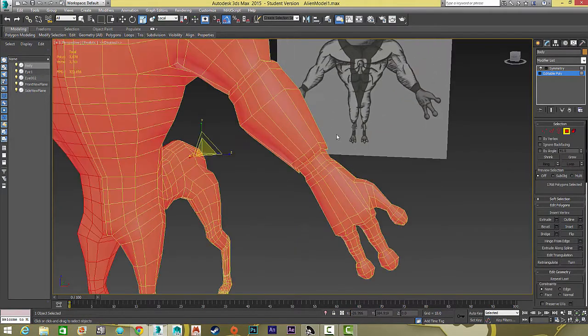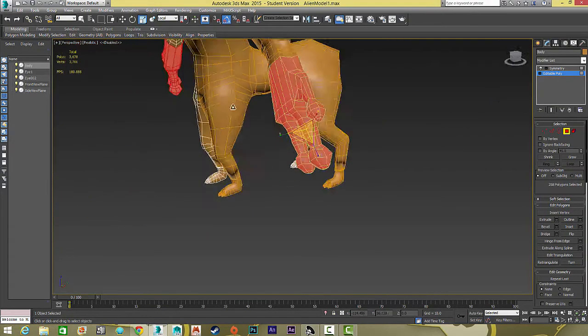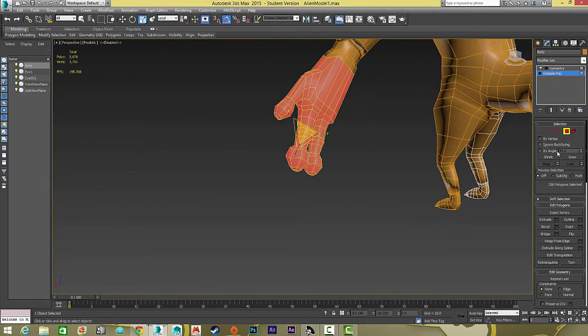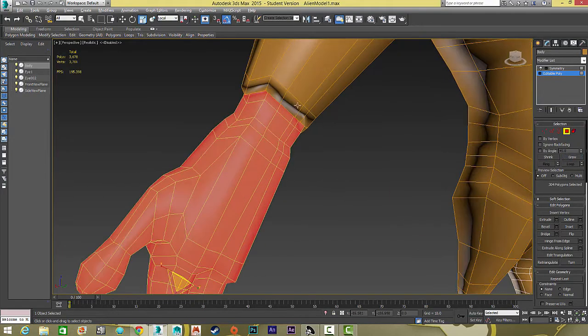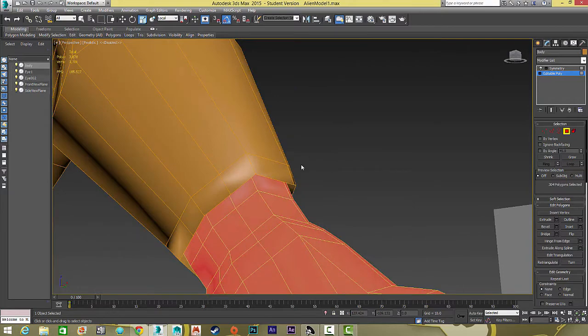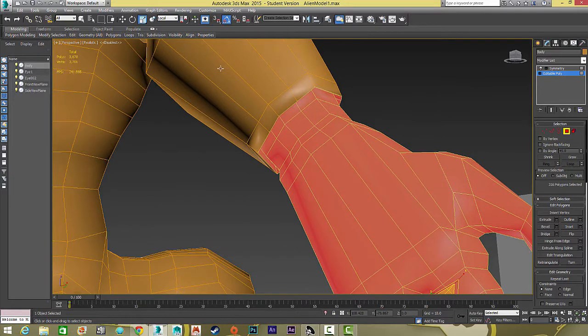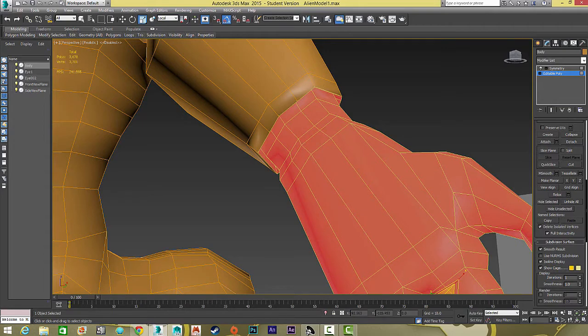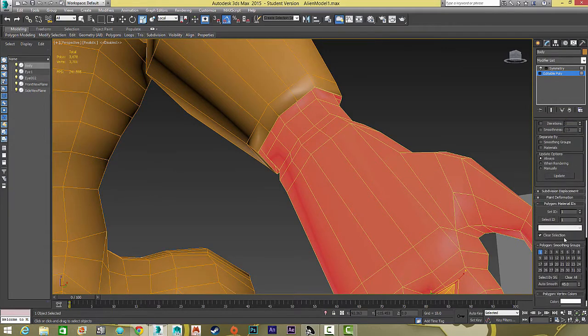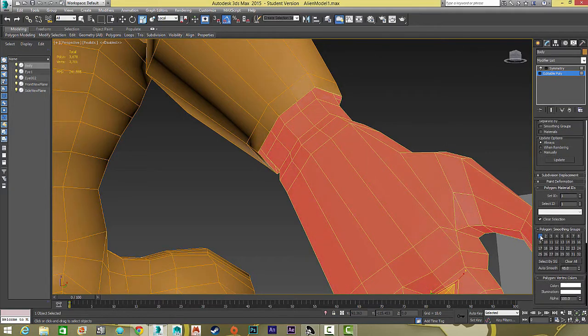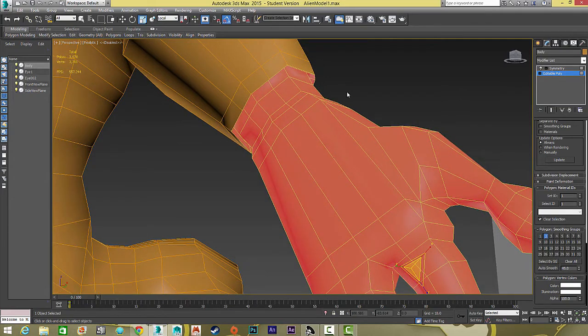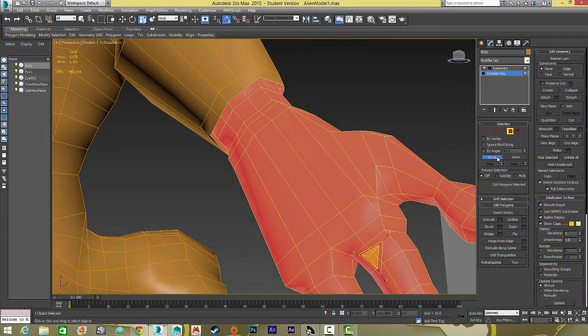So any areas that have more than a 30-40 degree angle should have a different smoothing group to them. So what we're going to do, let's start with the hand for example, is let's drag select all the polygons for the hand. Let's click grow a couple times, all the way until the inside loop there. We're also going to do it one more time. So grab that. So the outside, this area up here is going to be smoothing group 1, and then we're going to switch between 2 different smoothing groups for the hand. So since this is a 34 degree angle, we're going to change this to smoothing group 2. So how we do that is turn off smoothing group 1 and then add smoothing group 2. Don't ever add more than one smoothing group to a selection. You can, but it's just not the better method. Okay, so next thing I'm going to do, let's roll this out for a second, is let's go shrink one time.